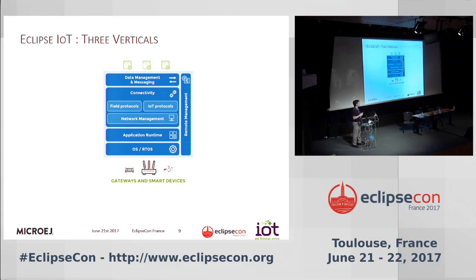So these devices are pretty powerful. They have a good level of connectivity, whether it's Ethernet, GSM or wireless Wi-Fi. They can run complex software stacks. Typically they run Linux, and on top of Linux they run a Java SE Embedded version, and on top of that they run an OSGi stack, right? And they can be remotely managed and dynamically updated in the field. Some of them can even do some local processing. They have enough power that they can start to process the data that they collect before sending it to the cloud services.